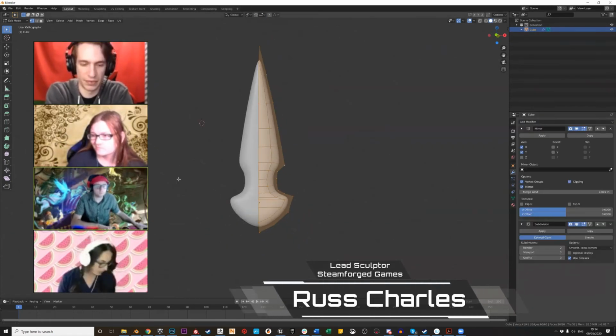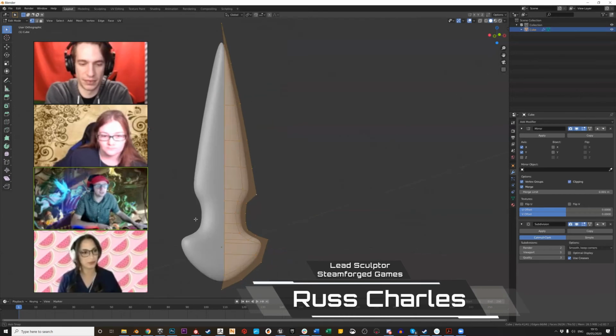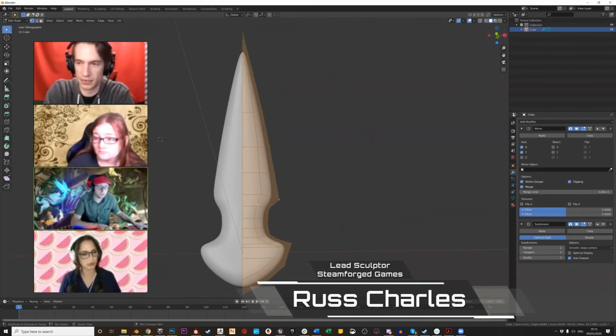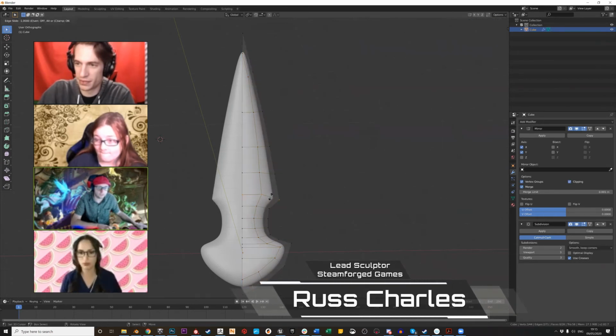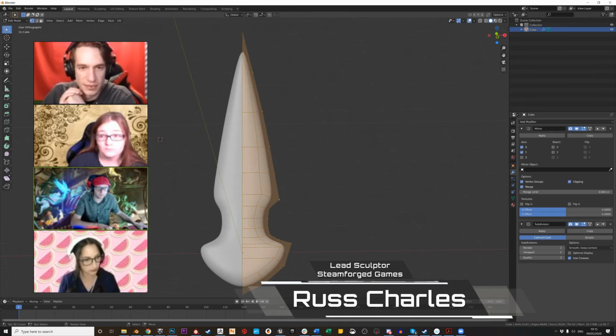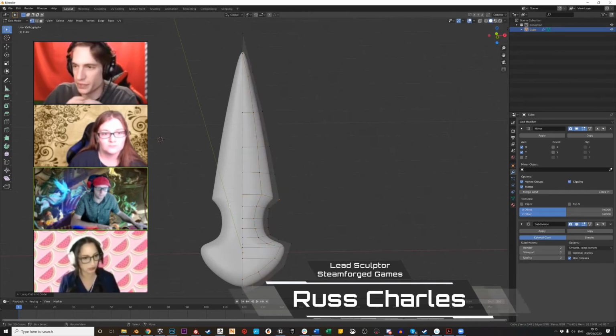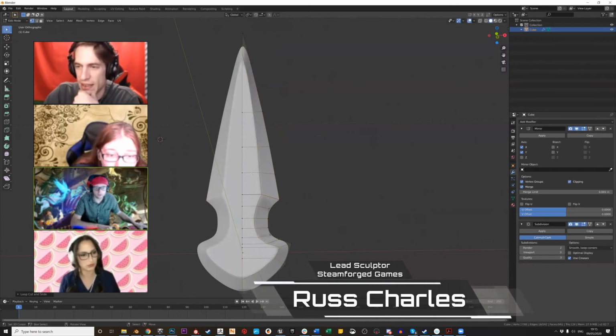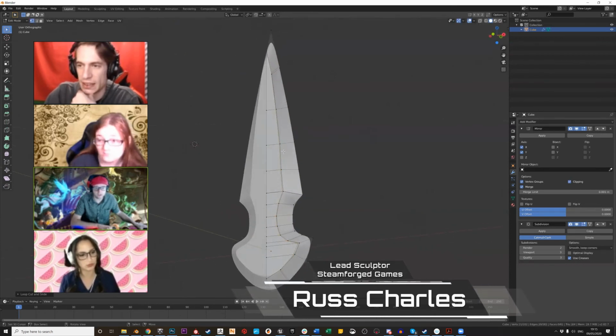So the places we're targeting the loops is, I want them on the points where my curves meet my sharp edge. So I put one above and below that specific vertex line. So one there and one there, and that sharpens that edge up. And I want to crisp up these edges, so I put them on there. I want them on this edge.